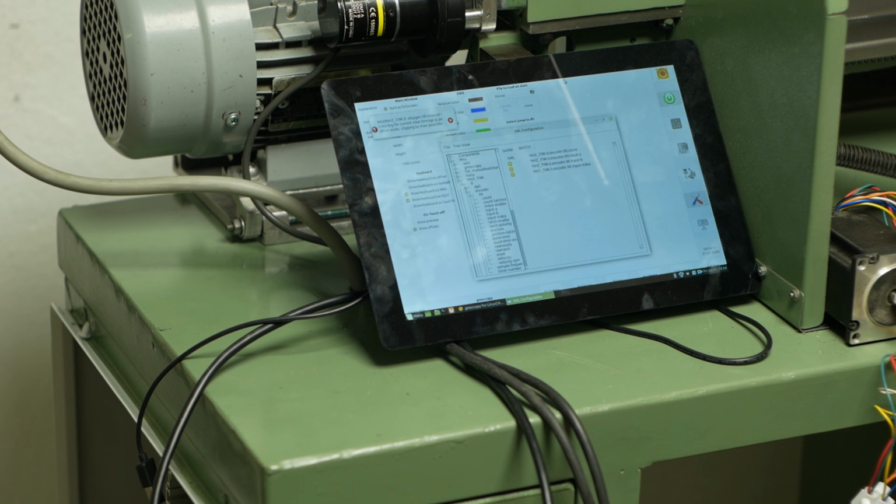Now that I've put all of the electrical components into the cabinets and wired them all up, I'm just going through and testing them. So the first thing to test is the encoder. As we turn, we can see that the encoder count changes in both directions. Both channel A and channel B are working. And somewhere in here, hopefully we'll see the index. Oh, there it is. So the index is also working. Cool. So that's that done.